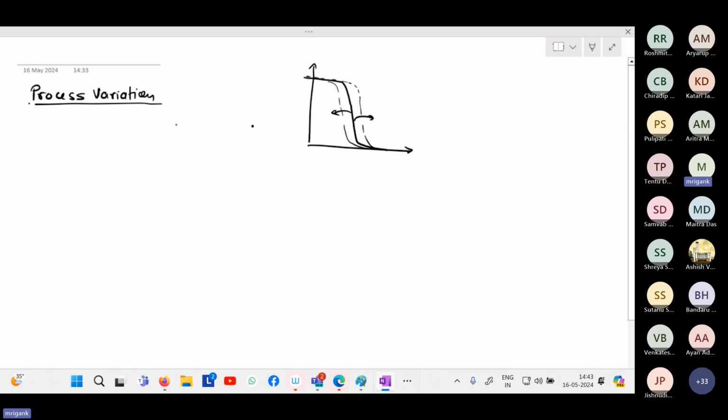Probably it would be good to use some slides there, but right now I'm just going to draw and explain. So first thing is that for the fabrication process, there is a silicon ingot. There is a very highly purified silicon, something like a log, and from there we basically create wafers. So these wafers can be, say, 12-inch wafers, and from there we are slicing this highly pure silicon ingot into wafers.